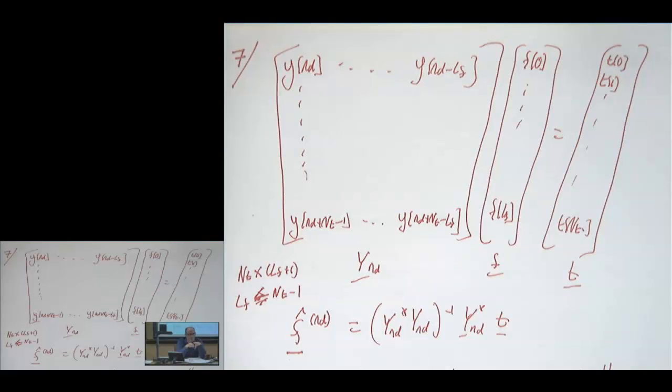But if you send in a sum of a whole bunch of sinusoids, then you could decompose that and build up enough information to estimate the channel. A sum of a whole bunch of sinusoids would look kind of like white noise, or basically a random sequence. So there is a lot of value in picking a very good input, so you can estimate the output.